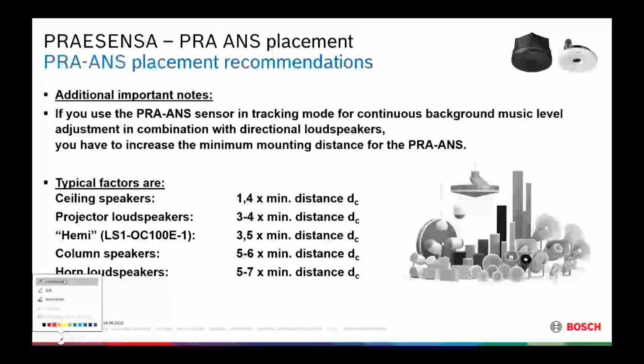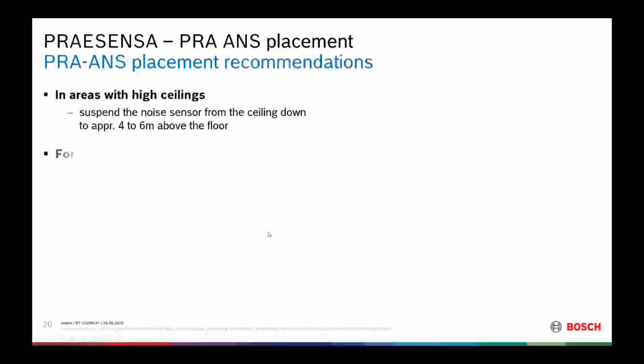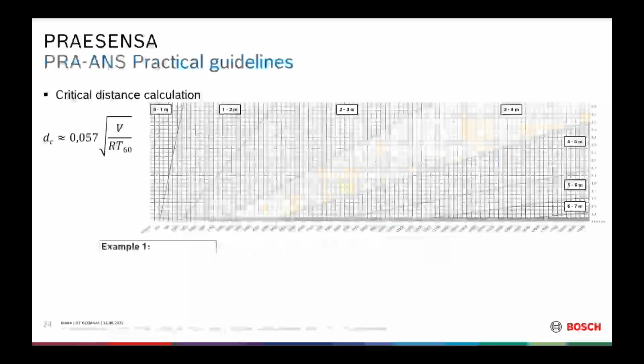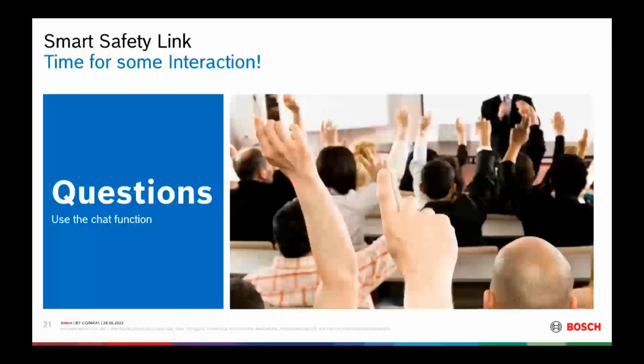Okay, good. Then can you afterwards compare multiple ANS with each other to see if maybe a certain ANS is overspecified or badly placed? Overspecified means, can I have any kind of indication whether I could do the same thing with fewer ANS in the same zone? I would also read it that you have too many sensors. Maybe you can do with less.